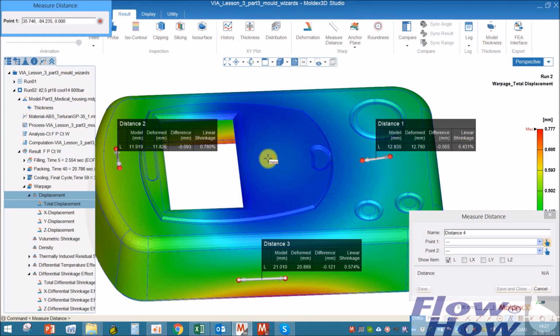So if you make the packing pressure higher, you will overpack this, and this shrinkage will be even lower, but you will also go down in linear shrinkage here. So designing the plastic part is the most important. These were the results that I would show here.